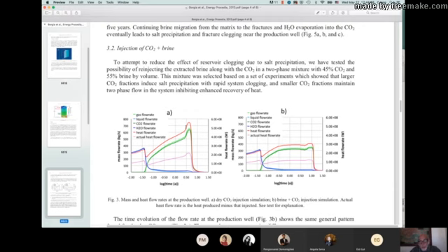But this is more difficult, because if you want to flush the system with fresh water, then the water will not go where the salt is, because the salt is clogging up the system. So it's not very easy to get around this, and the best way is to produce earthquakes that will fracture the rock and fracture the salt and allow the system to be open again to fracture permeability.